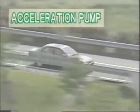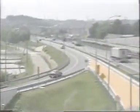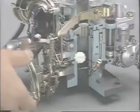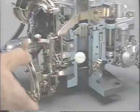Now let's take a look at the acceleration pump. We all know that to achieve quick acceleration, the driver needs to depress the accelerator pedal suddenly. The acceleration circuit is designed to prevent engine hesitation during such sudden acceleration. With the pump-type power circuit, when the throttle valve is suddenly opened, the pump lever depresses the pump plunger.